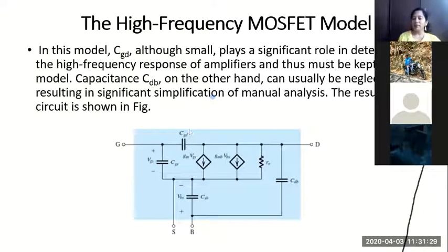So you have the gate terminal, the drain terminal, the source terminal, and the substrate or body terminal. In our original model, between the gate and source, it was an infinite resistance. We did not have anything there in the previous hybrid pi model which we used to write, right? But now there are device capacitances coming into the picture. There is a device capacitance CGS coming between the gate and source terminal, and similarly between the gate and drain terminal.